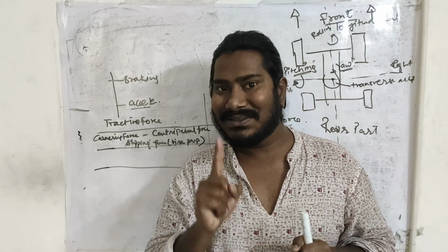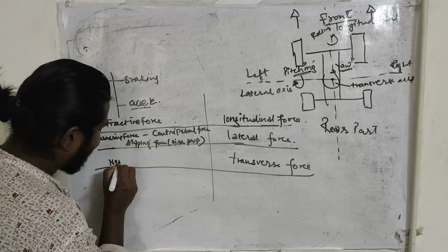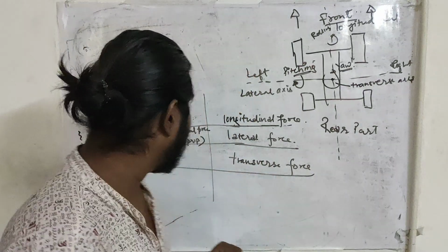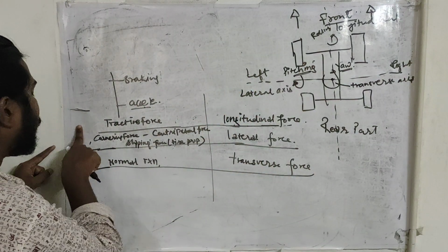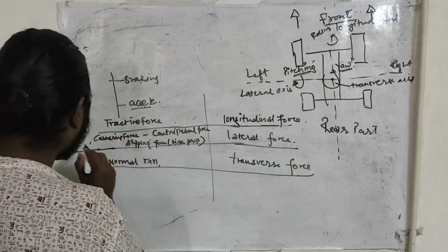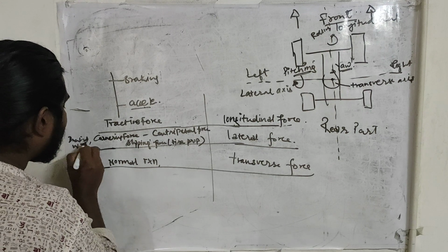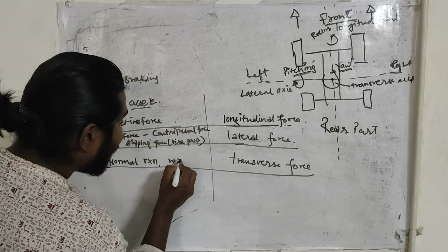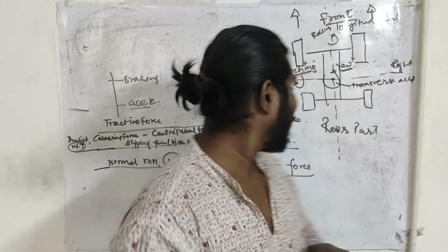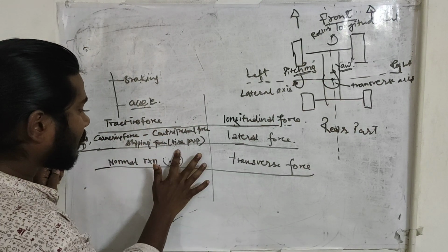Transverse force, what are those transverse forces? The normal reaction of the tire, right? Or whenever any weight transfer occurs. See here also, if any weight transfer occurs whenever you make a right or left corner, the weight transfer will occur in the opposite direction, right? The inertial loads or change in weight, or I can say the weight transfer. Here also I can say the weight transfer. You got this thing? Sure? Or even in the longitudinal axis, those forces.